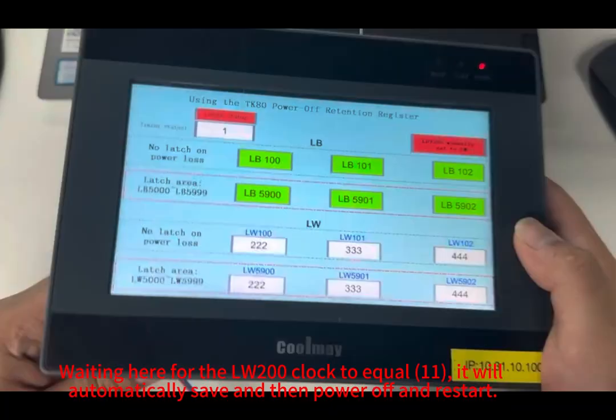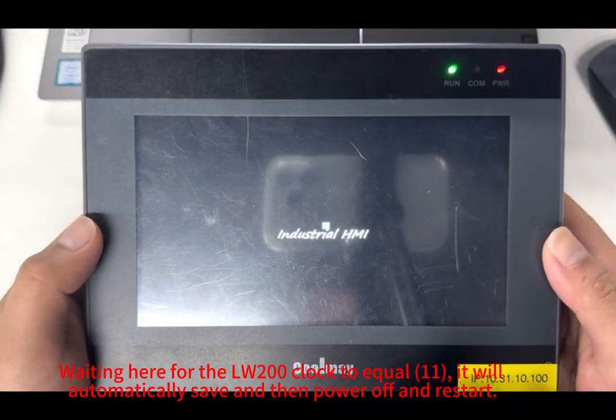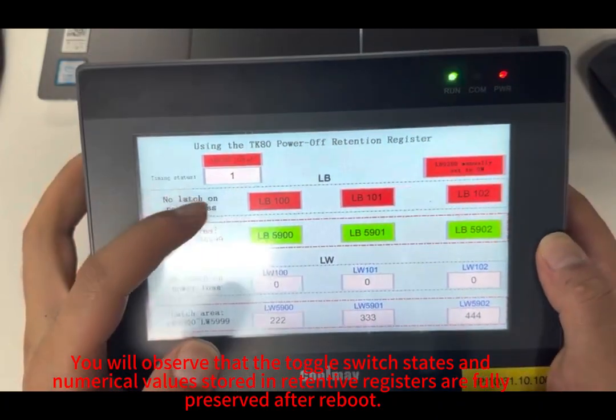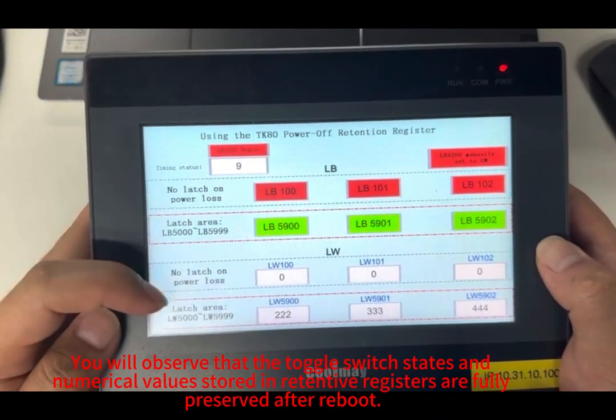Waiting here for the LW200 clock to equal 11, it will automatically save, and then power off and restart. You will observe that the toggle switch states and numerical values stored in retentive registers are fully preserved after reboot.